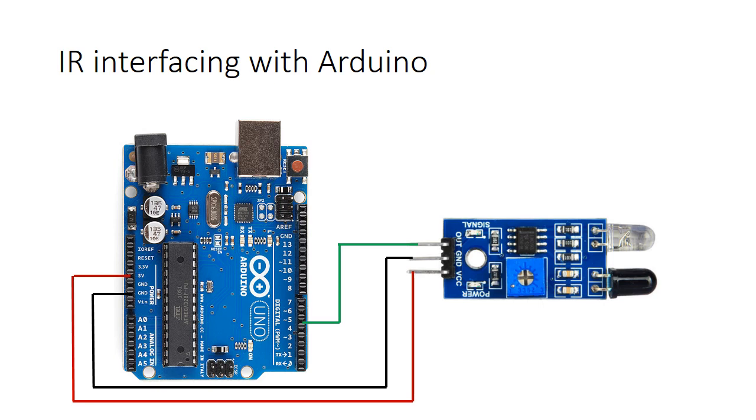This is the USB port. Here we connect this USB port to the computer USB port, and this port is basically used for programming this Atmega 328 IC. Here we can apply the power through the adapter or 9 volt battery, and this is basically the voltage regulator. This is the reset switch. Here, as we know, the IR sensor has 3 pins: output pin, ground and VCC.